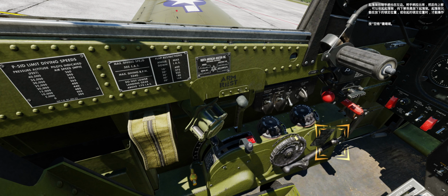The landing gear control handle is also on the left side. The handle is pulled in and moved up or down to raise and lower the landing gear as desired. The gear should only be moved when it's locked in either the up or down position.